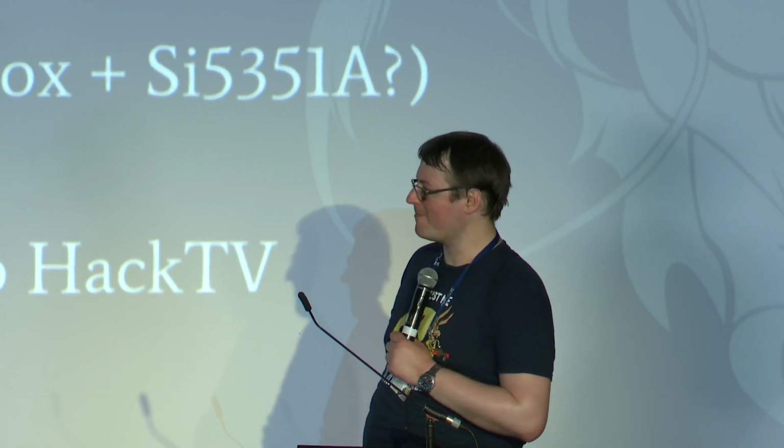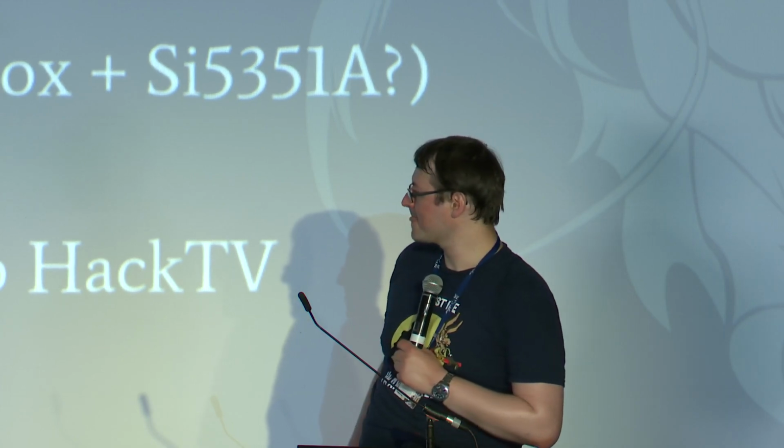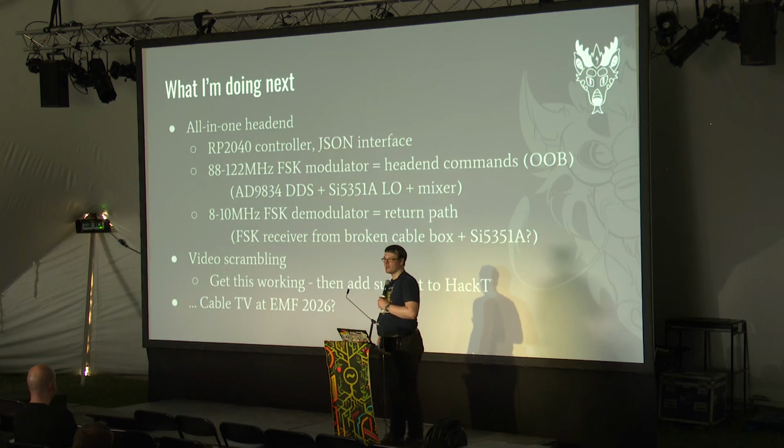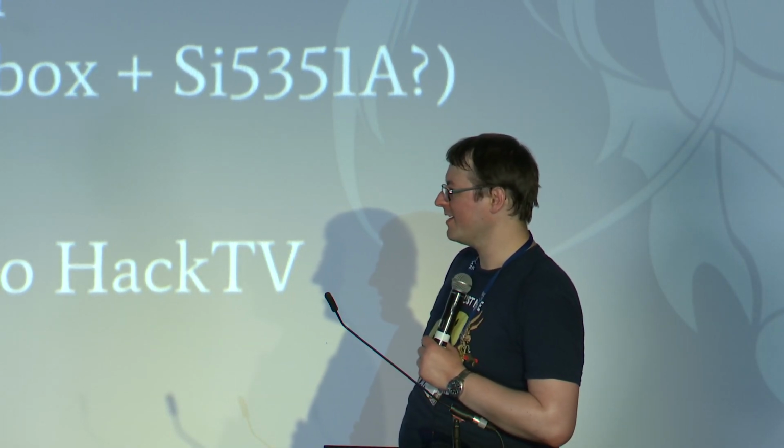But I also have a video scrambler, and this is a thing that I've been working on recently. There's a tool called Hack TV which can generate video signals using a SDR radio. So I'm working on adding the video scrambling to that, and that will just, if someone picks up one of these cable boxes, you can generate both the FM downlink with the SDR and then generate the video signal. But obviously, if you've only got a single channel SDR, you can only generate one at a time. But that would make it very easy for people to get involved in this.